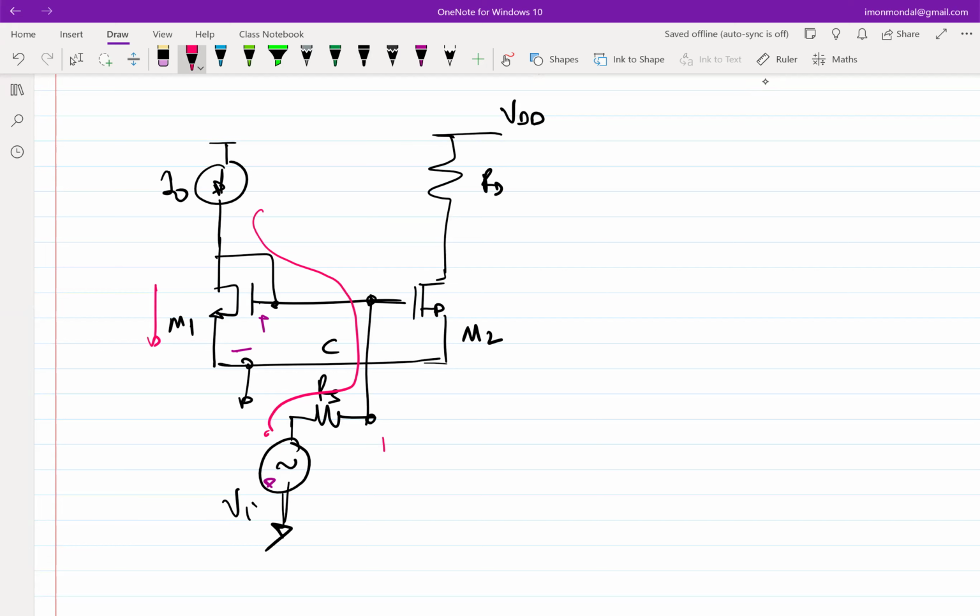Okay, fine. So the moment we have a capacitor, we have to figure out what is the value of the capacitor that is necessary to ensure that it behaves like a short circuit for the frequency of interest. We don't even have to do much calculation. It's all related to time constants, right? So what is the time constant associated with the capacitor? It's Rs times C, or it's something else.